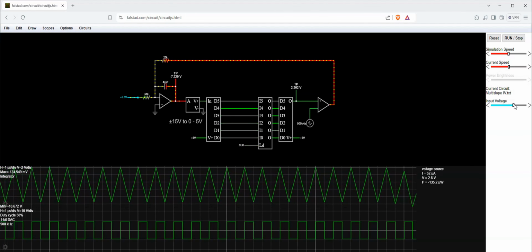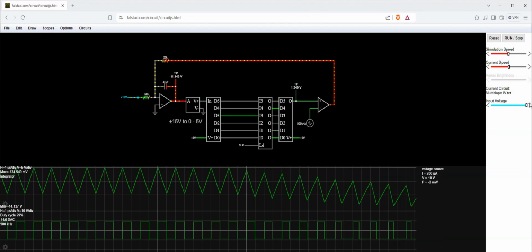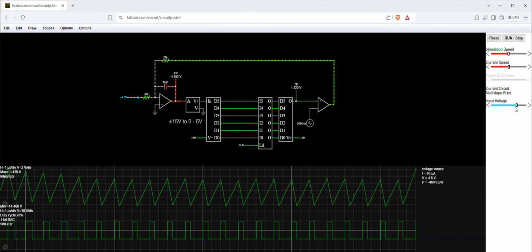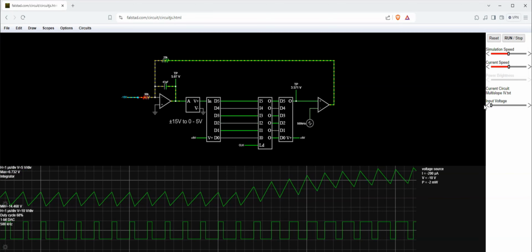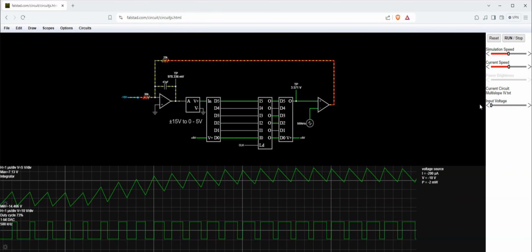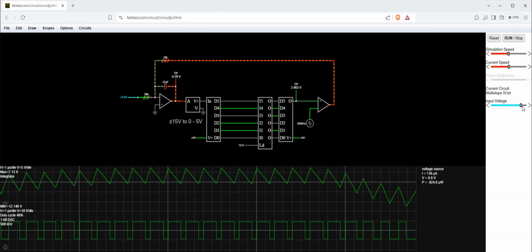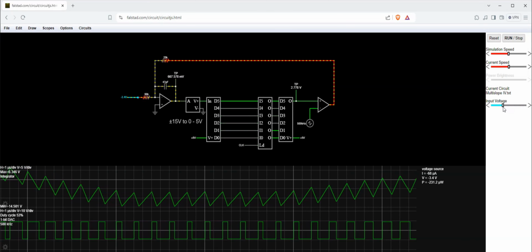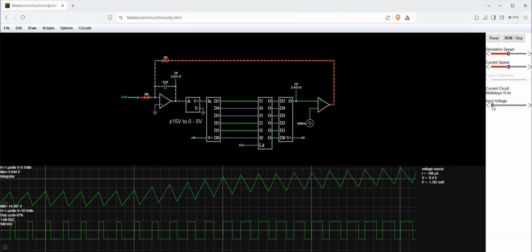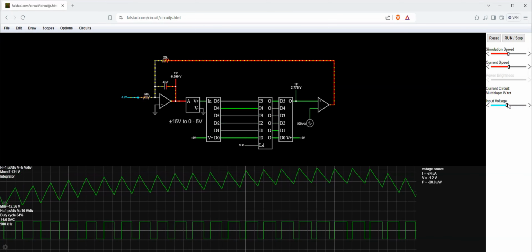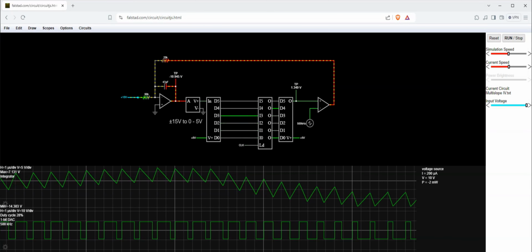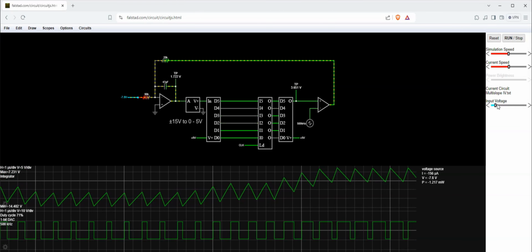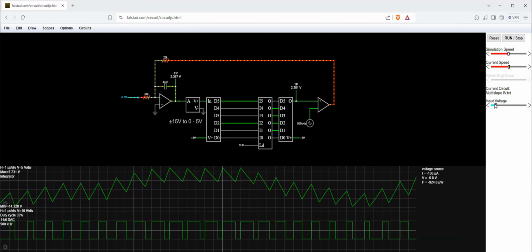Implementing a simplified version of this modulator in Falstad reveals 2 problems. The first is a DC offset on the integrator that depends on the input voltage. In a precision ADC, this can lead to a few problems. First, a large integrator swing risks saturating the integrator op-amp to the supply rails, and operating close to them reduces linearity. Second, a large DC component on the integrator waveform exaggerates the effect of dielectric absorption. Third, a larger dynamic range is expected of the coarse ADC that digitizes the integrator.